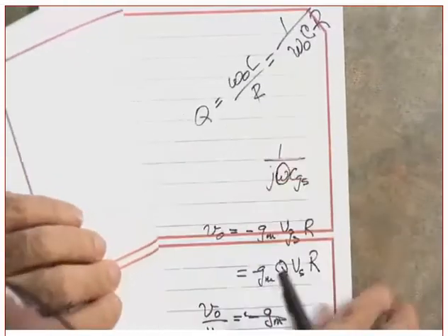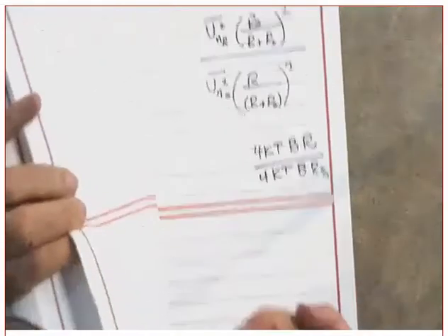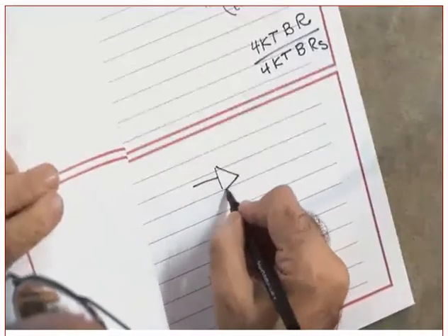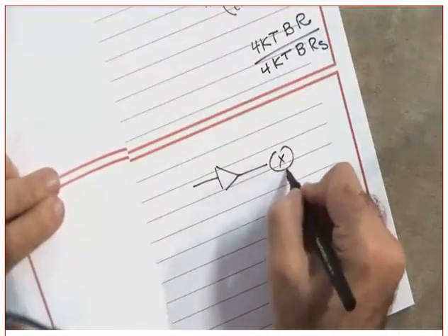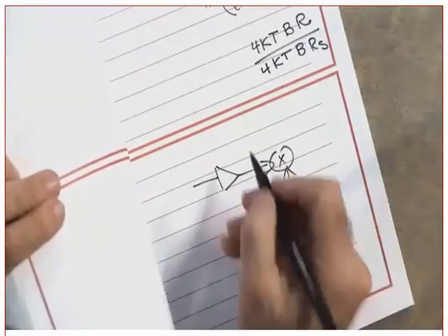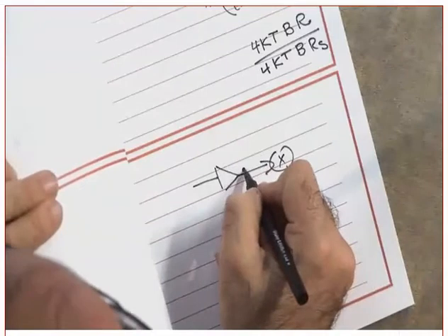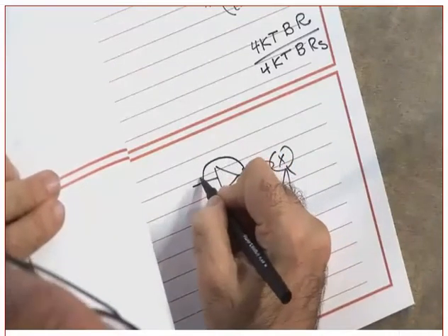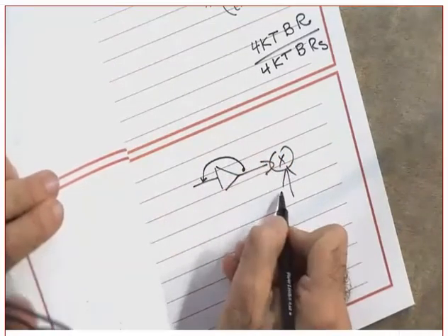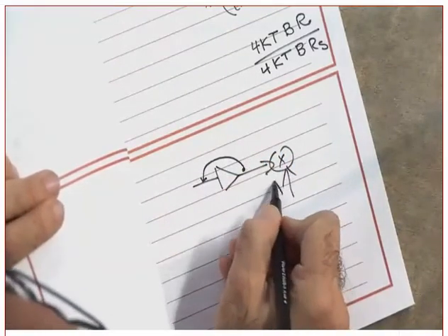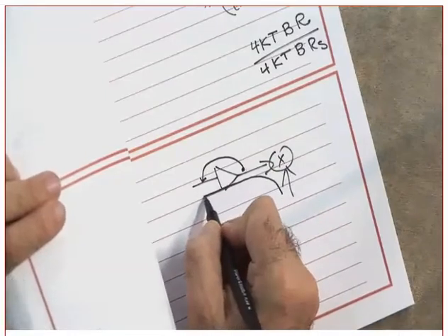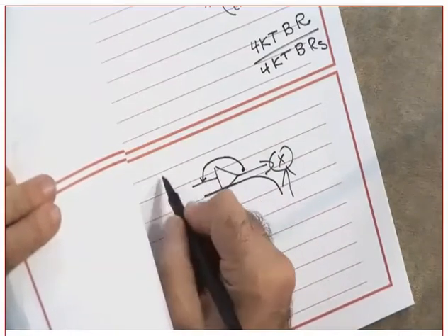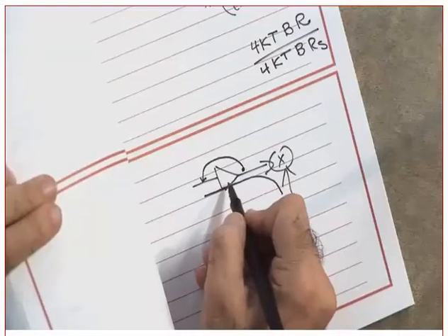The problem is that if you have the amplifier like this, this is the LNA. Remember, the LNA will be followed by the mixer. And if we do have leakage from this guy to this guy, there is a possibility that this local oscillator will leak. Are you following me or not? All the way to the antenna.